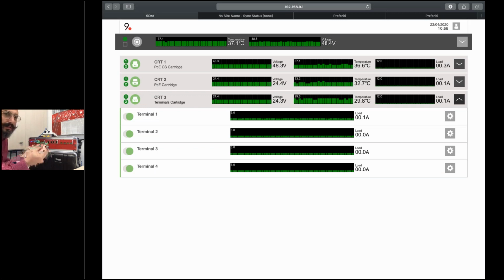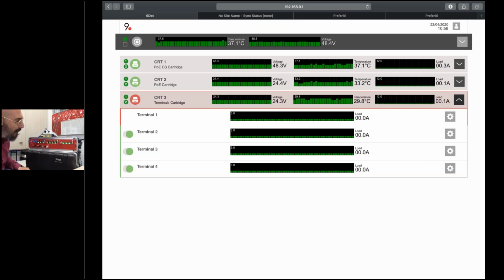And let me show you something. What happened in your installation is if you connected this kind of connector, you can see it, it's a short circuit. Okay, let's do it. Boom, no problem. The port now is on error, as you can see in the web interface.